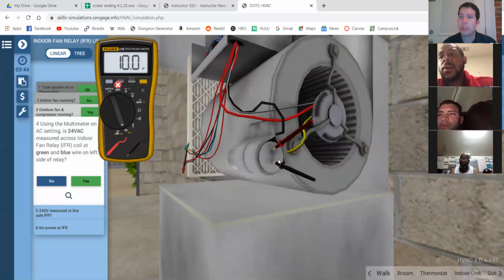After it's discharged, then you're going to put your meter on and check for microfarads. The trick with it is, I will say, give it a second. It does not read instantly. Microfarads take a minute to read because your battery in your meter actually sends a signal through the capacitor from one lead to the other to measure capacitance between the two. It takes a little while to calculate.